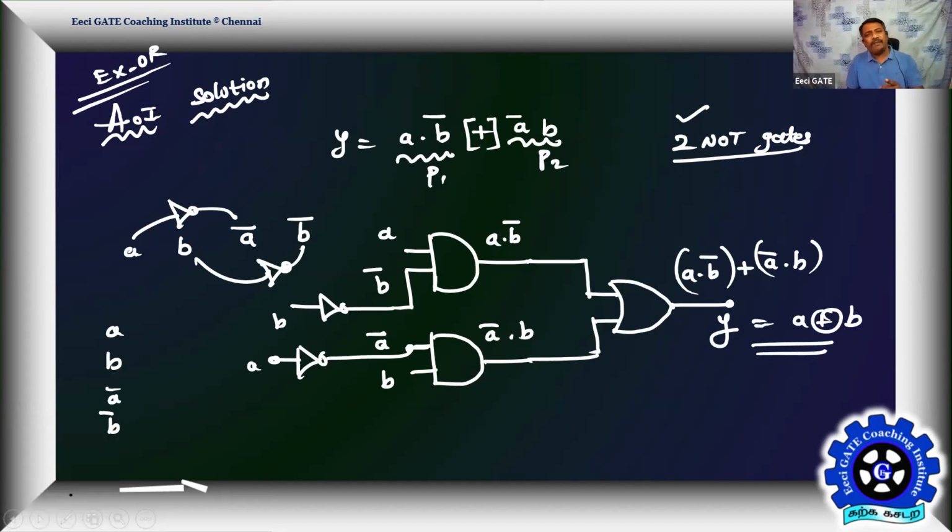If you directly implement it using AOI logic, tell me what is the cost of the solution in terms of CMOS. AOI is not an optimal solution. AOI is a beginning solution. As a student, you want to make things as simple as possible, so you have the free hand to choose n number of NOT gates, AND gates, and OR gates, because any logic function is going to involve products and sums only.